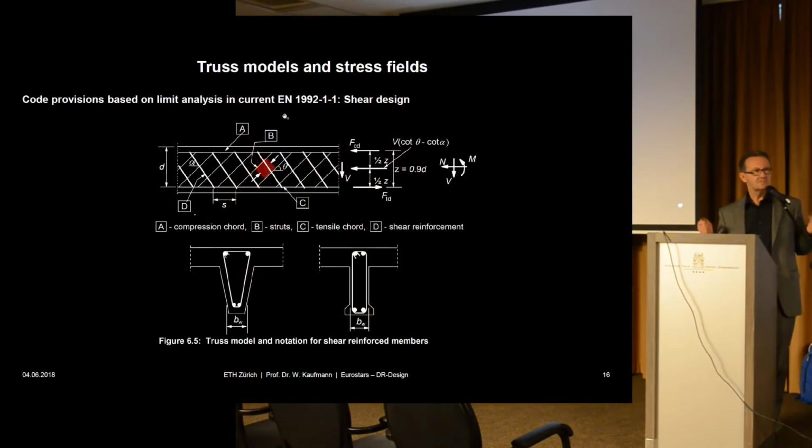And many of the methods that we have in the codes, for concrete structures particularly, are based on these limit analysis methods. And it would be good if designers were aware of this, because having them in the code is one thing, knowing why is another one, and knowing that there are limitations is the third one. So these will only work if you have enough deformation capacity. So we need ductile reinforcement. You cannot put in some welded nets and expect that you reach the ultimate load. Then it's not a safe design when we design using this type of reinforcement, for example.